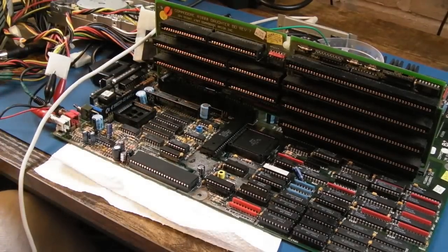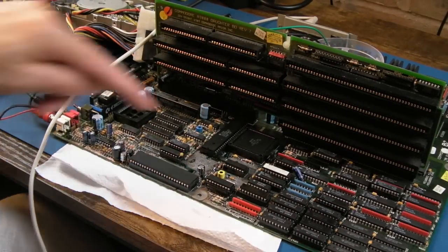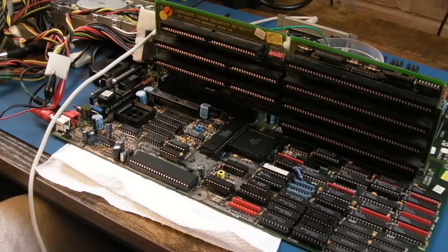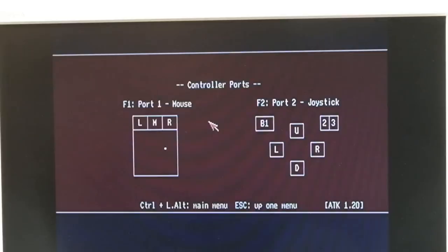35. So I'll flip the board over and try to work out where the traces go, because it's one of the long traces that runs down, a whole bus of them where they were super corroded, and I'll bypass that with a wire. Yeah, so I fitted a wire on the underside there. I'll show you that later. It's probably going to need securing with a bit of hot melt glue.